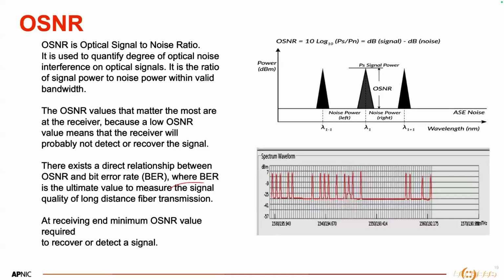So, this same power for each wavelength, it's only needed if we are using an amplifier, right? If they're passive mux, then I think... For DWDM, your lambdas realistically have to pass through amplifiers. Okay. Not cheap amplifiers in DWDM. So that is the main thing.